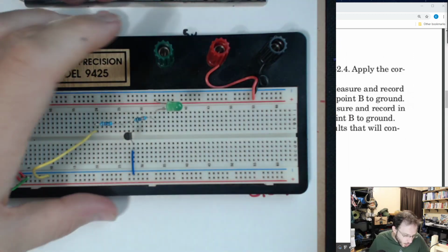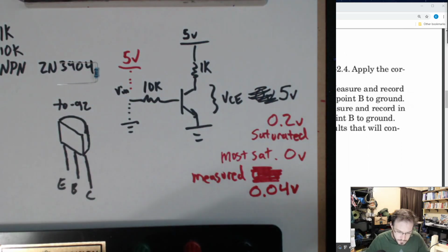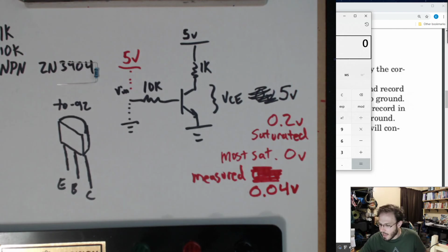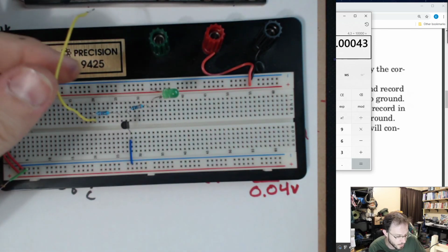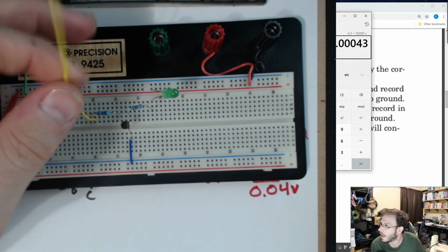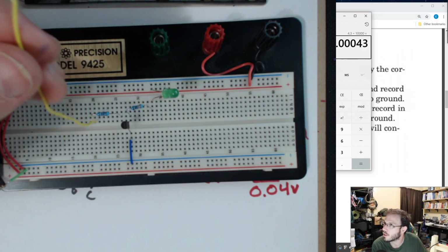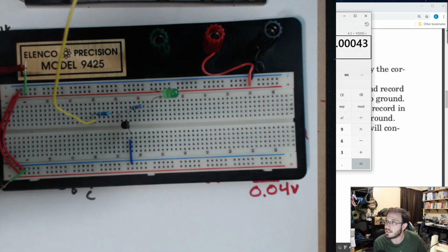And you can go ahead and calculate that. Let's say 5 volts minus 0.7 gives us a 4.3 volt drop across that resistor, and that resistor is 10K. So 4.3 volts divided by 10K is 0.4 milliamps. So we only have 0.4 milliamps going through the yellow wire, or being sourced by our 8051 or our microcontroller or our FPGA. So that's a great situation to be in.